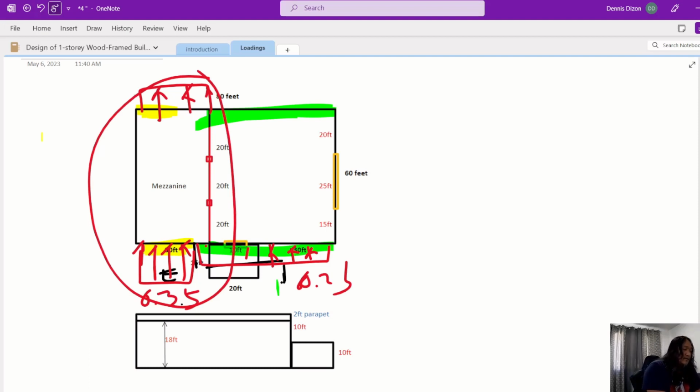Now, what I typically do when I analyze this one, because in this case, this is your load application, and then this diagram will produce a rotation. It will produce a rotation here. I mean, this is the proper way. It will produce a rotation, and although the wind is going in that direction, because we have this rotation, we have a load acting on this wall.